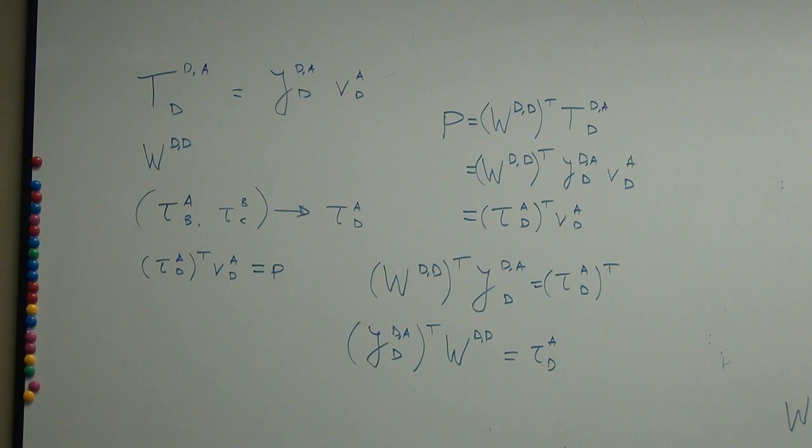When you do tau equals J transpose F, given a wrench, there's only going to be one set of torques. Yeah. But the other way around, given a bunch of torques, they can result in different effective wrenches.